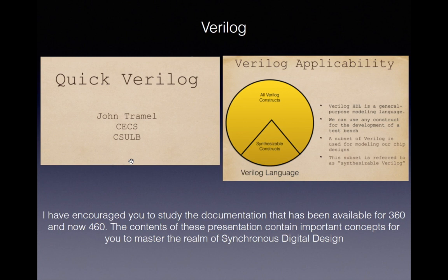since we have a particular arena we're playing in, chip design, specifically FPGA design, we use a subset. That subset is referred to as synthesizable constructs. The rest of the language is available to us in our test bench design, primarily because we don't synthesize it.